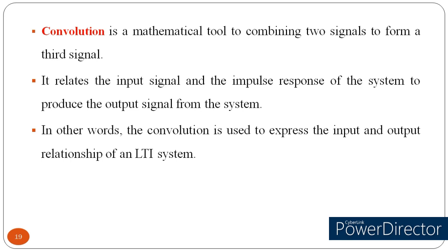As I said, convolution is a mathematical tool that is used to combine two signals and to form a third signal, and it relates the input signal and the impulse response of the system to produce the output signal from the system, or in other words, the convolution is used to express the input and the output relationship of an LTI system.